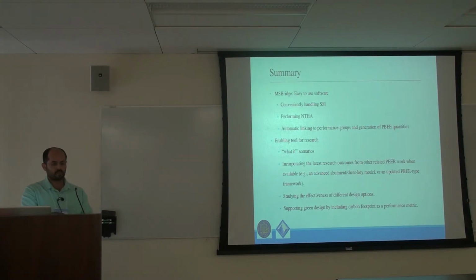The problem with not doing it in terms of direct differentiation, which is sort of like finite element, and doing it by finite difference, is that you could get very wrong results, because by finite difference you perturb a parameter. And if you're doing nonlinear analysis that has convergence criteria, your perturbation of the parameter and the resulting perturbation of the response may not correspond. Some of the perturbation in the response could be because of your convergence criteria in the nonlinear analysis. So it's very problematic. If you make a very small change in the parameter, all of the change in the response could be due to your convergence criteria. So doing finite difference correctly is very tricky.